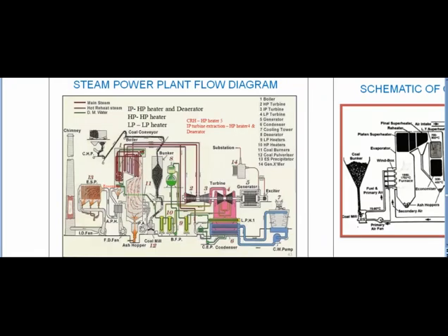This is total how the flue gas movement takes place through the furnace, then it comes out from the furnace through air preheater, it goes to ESP, then from ESP it is being sucked by ID fan, and then through chimney it is exhausted into the atmosphere.